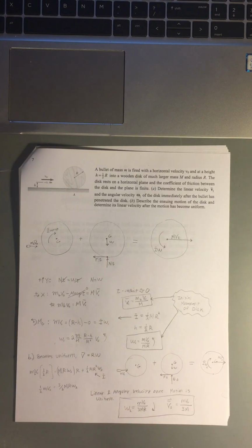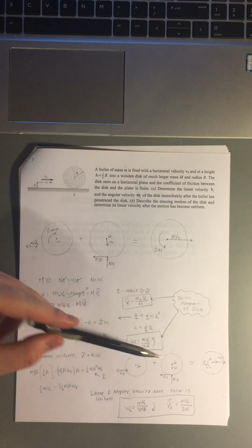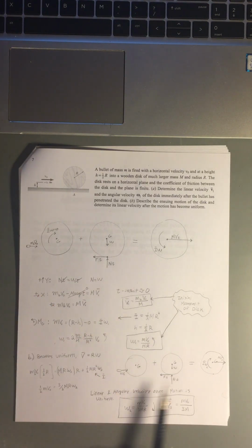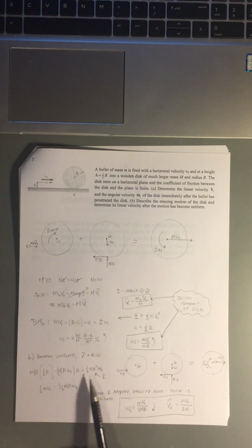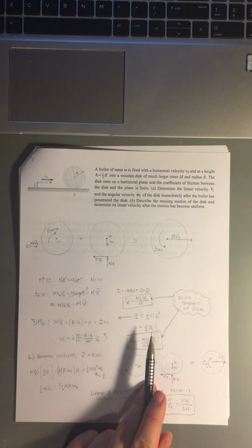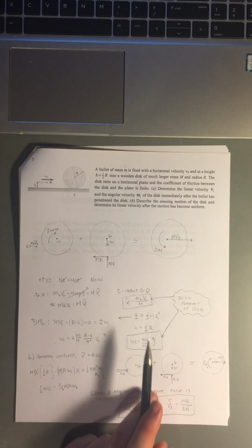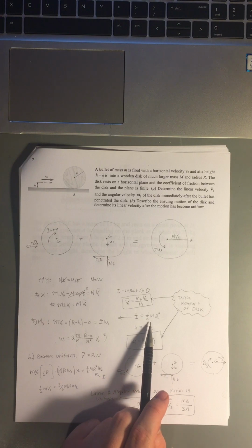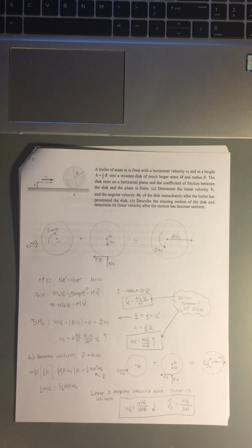And then like a similar process from up above, we can use this diagram here we've created to write out our equation. And then this I term is the same one from up above. It's our inertia for the wooden disc, and so we can plug that in, and then we can simplify this to find out what our omega 2 is.